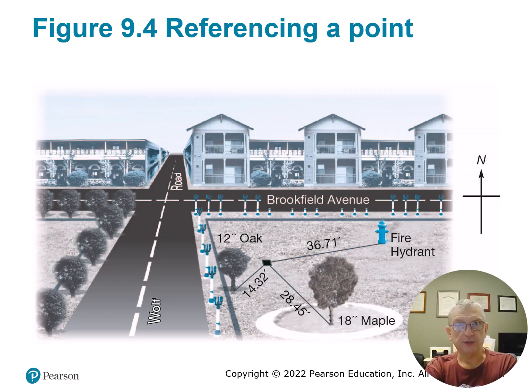Once you know where you're going to go, then you go set up the traverse. And you're looking for a clear line of sight. It's ideal to be near the property line, but it's not necessary. Especially if the property line is particularly thick, overgrown, or has a lot of fences around it, you might not even be able to set up on the actual property line if you wanted to. So you have to select places where the ground is typically nice and level, pretty firm. You're probably not in direct sunlight. You even have to think about things like, are there bee nests or ant beds nearby? Are you within reach of a chained dog that really wants to eat you alive? These things all come into play in the field.